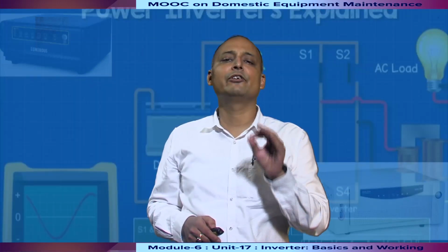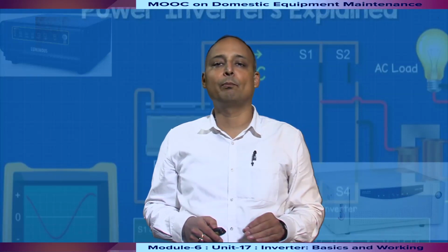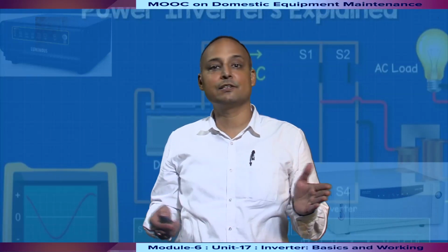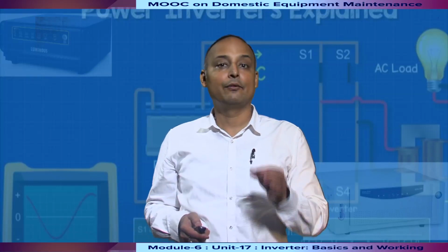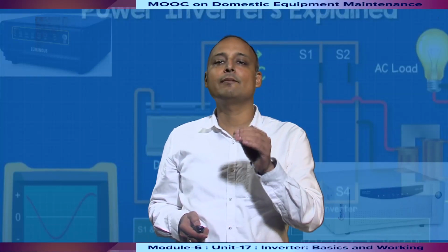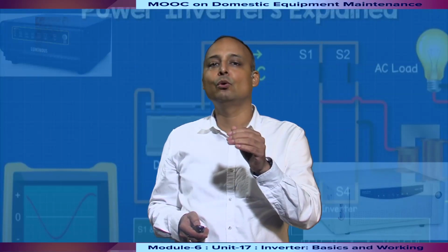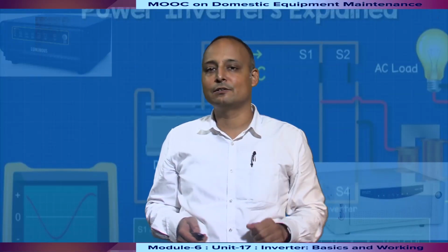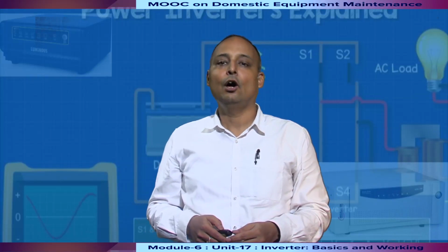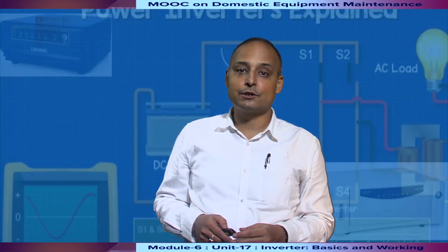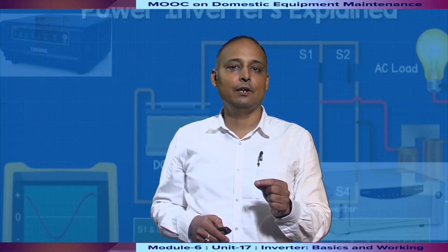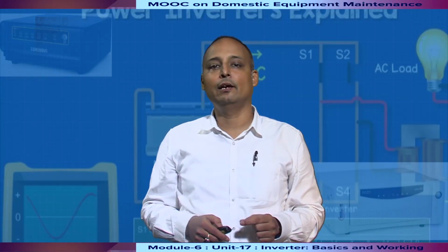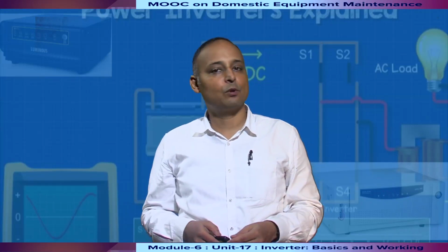Inverters primarily rely on batteries to store power that it can convert for use in devices in the house. Therefore, checking the water level in the battery regularly to ensure that it is within the recommended range is crucial. A lower water level reduces the battery's efficiency and, if unchecked, would make the battery fail to charge or discharge properly.